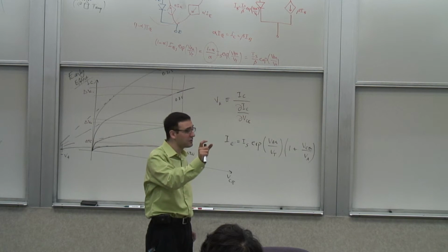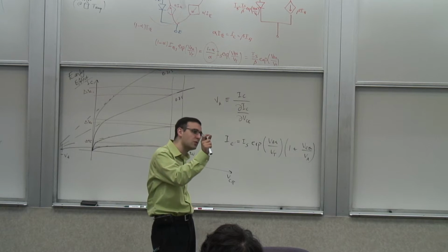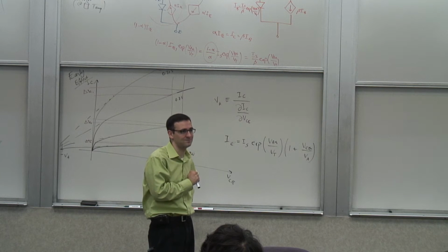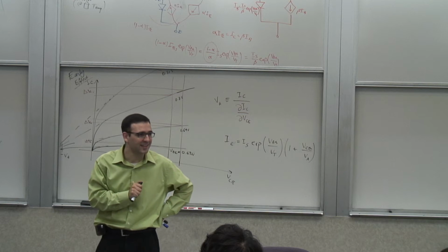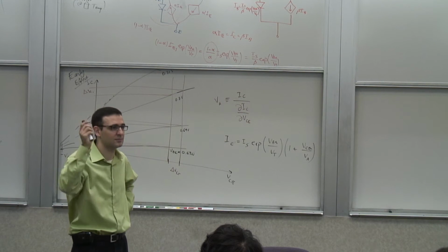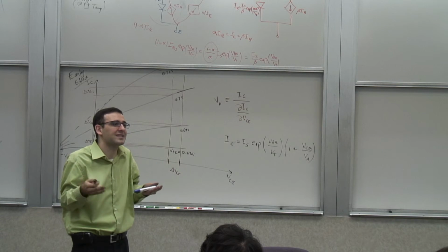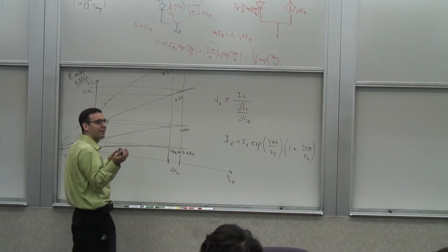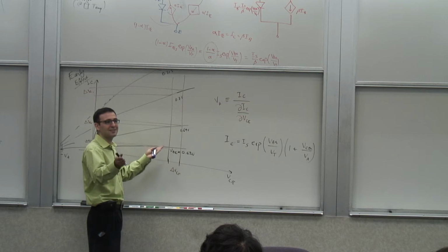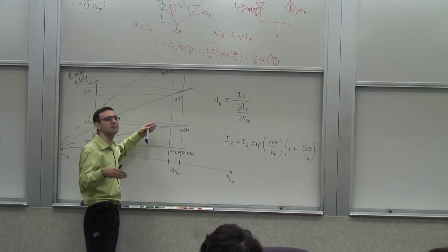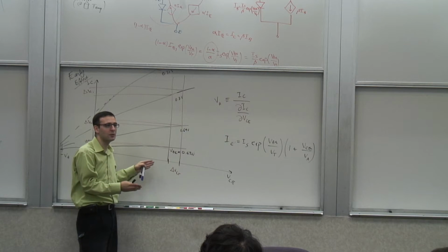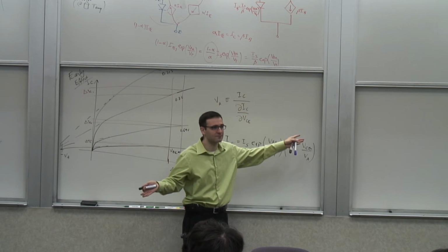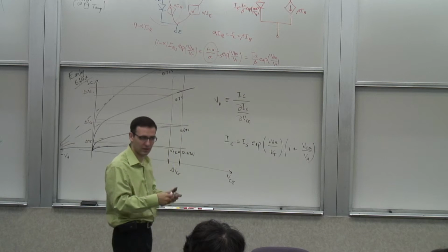But now you also have to remember one thing: the fact that there's the square root dependence on the depletion region also relied on another assumption, which was the abrupt junction. If that assumption is not held, the square root assumption is not held, it's some exponent, right? It may not even be square root. In most practical cases, it's not. So it's some exponent, and you look at the first order Taylor term of that exponent, that's linear. So short answer, it's not exactly linear. It's an approximation, but it's a reasonable approximation for the range of voltages we deal with. Otherwise, you have to have this exponent that varies from case to case. So it's a very good question.